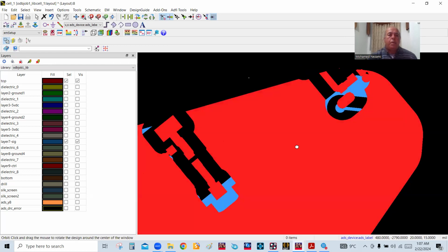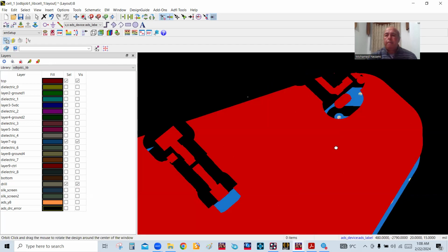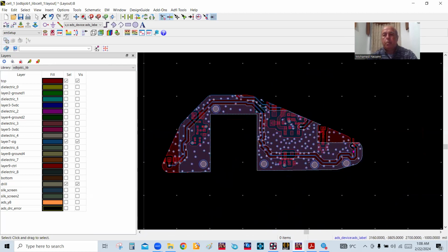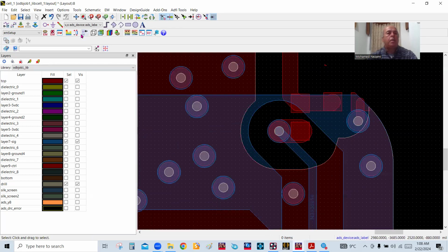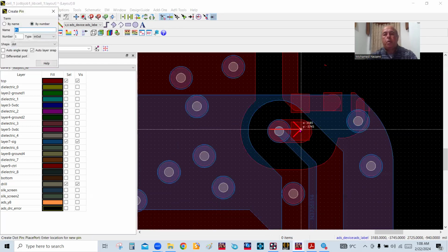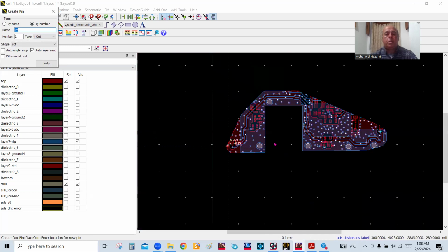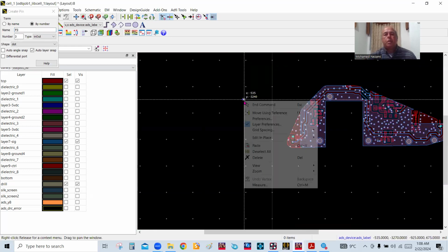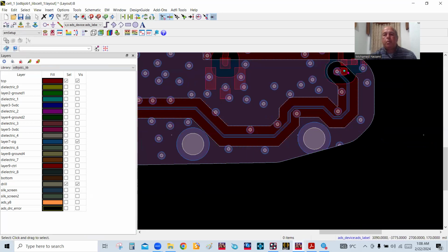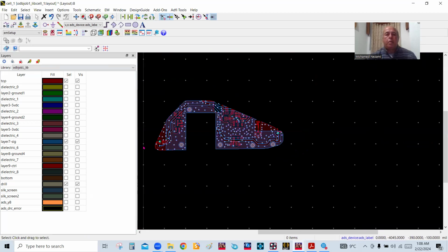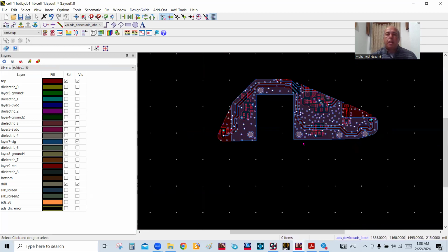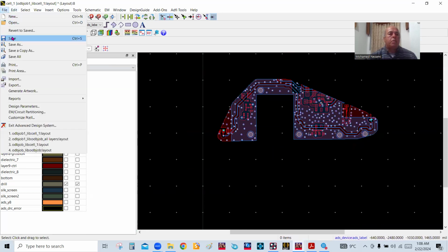So let's put the drill on. So what we're going to do is put a port on this side, on the top layer, and another port on the other side. Of course, we don't have anything to do with layer 7 or the strip line layer, because we basically go in from top down to that one, and then we go back in there. So we don't need to put any excitations on the 7th layer.